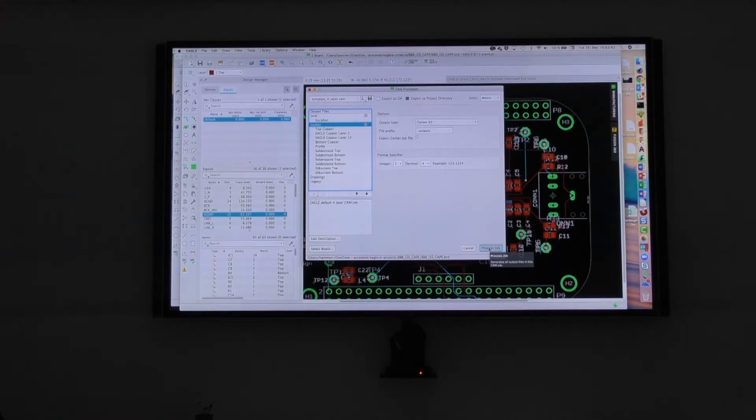So to say, you don't have to take care of anything in a regular usual board. Of course, there can be some special things if you use maybe your own layers. Because you have drawn something, you want to have a special logo printed or something like this, you have drawn this in a user-defined layer, then you would simply do a right-click here, add a new Gerber output, set which layer should be output, in which file should it go, what device you want to use for and so on. That's one thing.